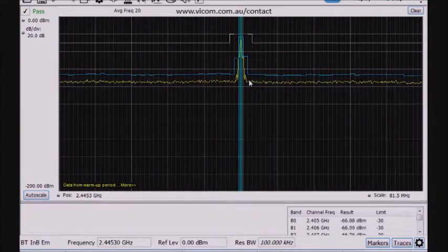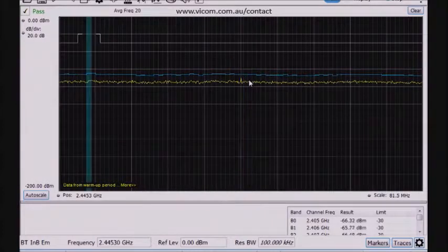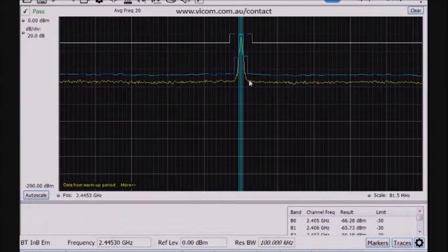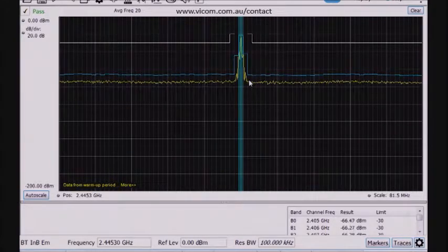That's an important test to make sure that you're not interfering with other users of the ISM band with your device. There the averaging didn't work, so it hopped around and searched for it again. By the way, this averaging problem goes away if I use the DPX display, the real-time display that's available here, but I don't have that available within this in-band emissions test. It's just the basic spectrum display. So that's the first test that I would do for EMI pre-compliance.